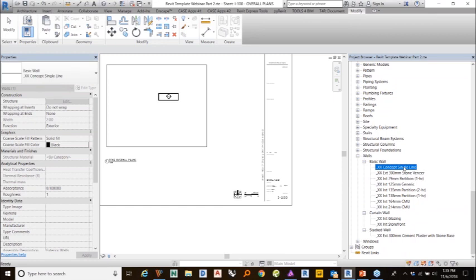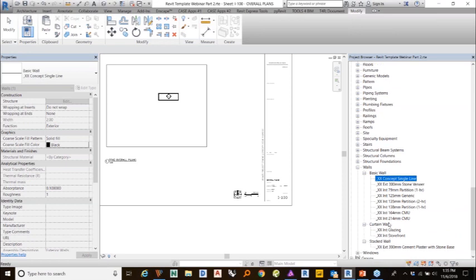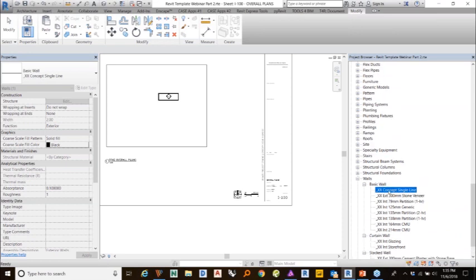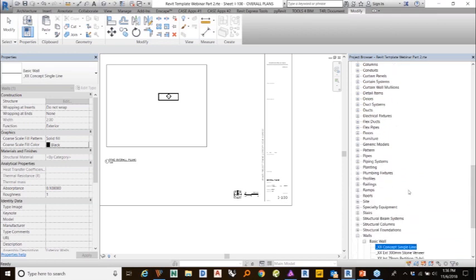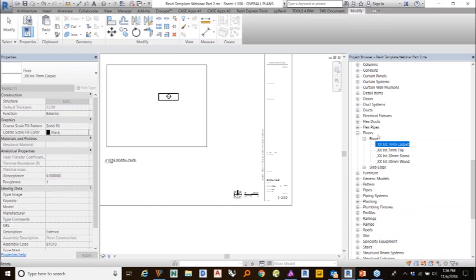They're not just generic. Another thing that you want to look for is that they have some kind of accepted naming convention. And for example, for this, we kept it pretty simple. The XX is the 2 initials of the project name. And so you know that these were built for this template for that project. And then you've got the out-of-the-box ones that live in there. Same idea for floors. I've got 4 floors just baked in here, and I can quickly pick one of them, duplicate it, and then make changes to it.